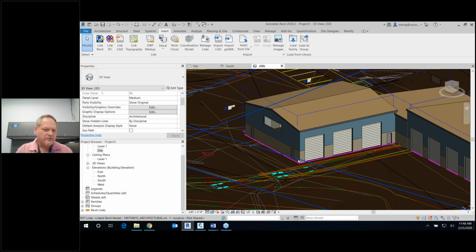Oh, that's fine. You can bring it into the architectural model, and that's always how I've done it. But I just got into trouble having all that extra CAD data in my working model. But there's no reason that now that you're on shared coordinates, you can drop. So I really will dumb down my CAD file at that point, right?